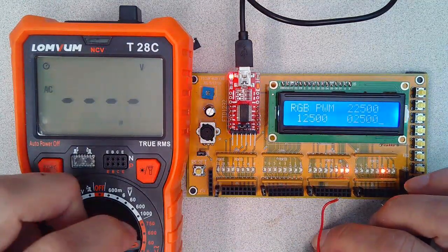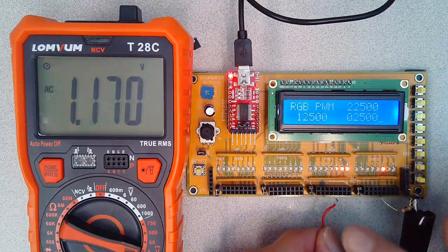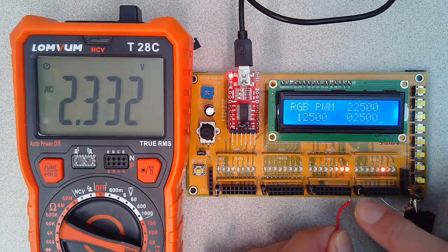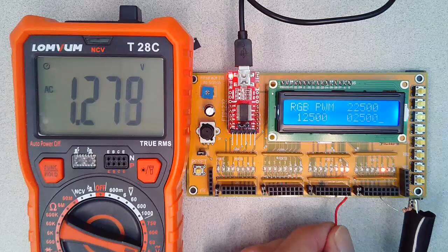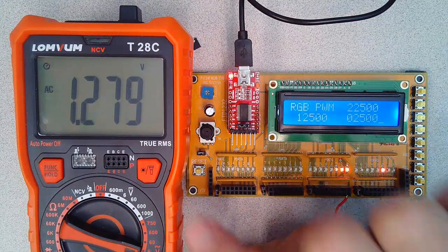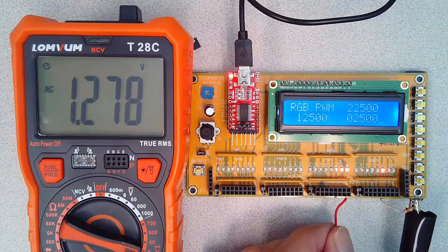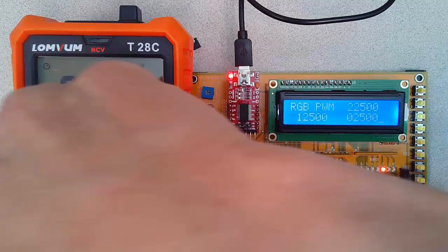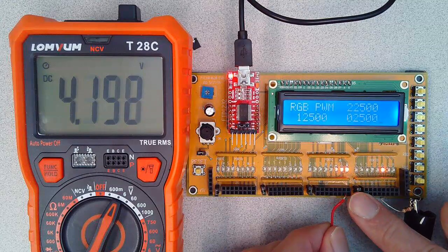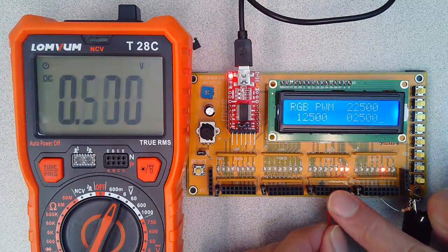I can also measure the AC voltage. So this is the AC voltage at 10%, at 50%, at 90%. Basically, AC doesn't tell you anything. If you think about it, AC's got 3 units: peak to peak, peak, and RMS. This is telling me the RMS voltage. If I think of peak to peak, the peak to peak voltage is always 5 volts. This is a square wave going between 0 and 5 volts. The peak to peak doesn't change. That's the AC voltage. Really what you want is DC voltage. So there's my percentage. And what that tells me is I can vary the percentage of on time.